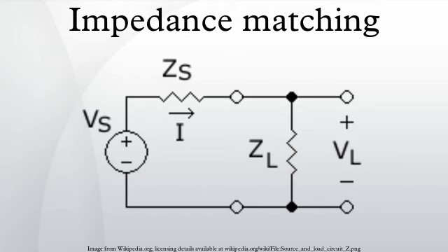Step transmission line: most lumped element devices can match a specific range of load impedances. For example, in order to match an inductive load into a real impedance, a capacitor needs to be used. If the load impedance becomes capacitive, the matching element must be replaced by an inductor. In many cases, there is a need to use the same circuit to match a broad range of load impedance and thus simplify the circuit design.